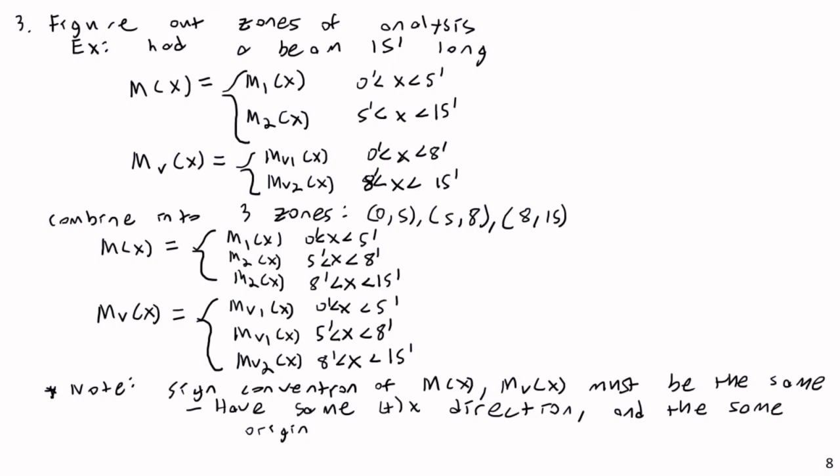And finally, there's a step 4 we can look at. Our final step. So again, it is important to keep all of our origins aligned, all our coordinate systems aligned. You can't exactly take an integral with 2 incompatible coordinate systems. For example, if one had x defined as 0 at the middle of the beam for some odd reason, then you'd have to define the other one that way, or define them both from the left end of the beam, or whatever it might be.